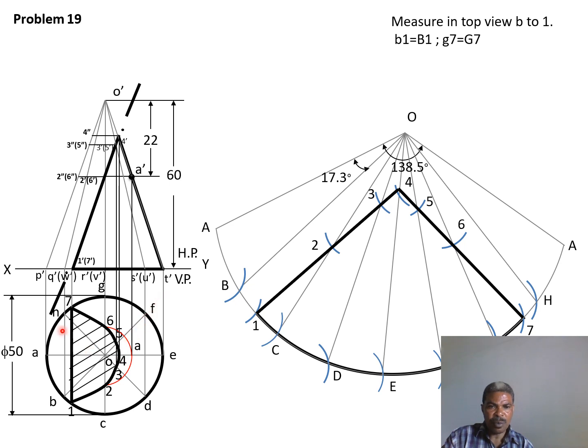So these lines indicate where it touches after it has been removed, these points here. So remember to project them at the very center from the division points. Then you project them back. As you can see here, the line goes to the center here. But this line indicates where it has come to cut this line. Then you project it downwards until it indicates the boundary for our curve here. This line is also projected to the outer line here, making 4.